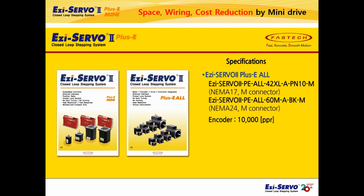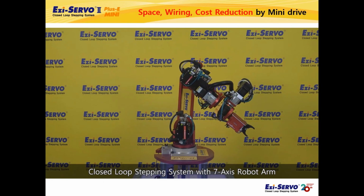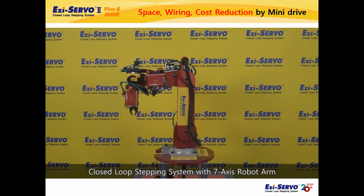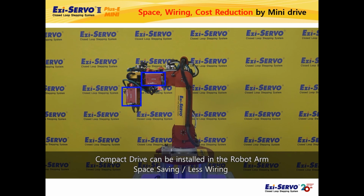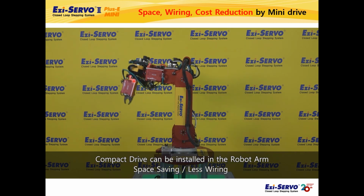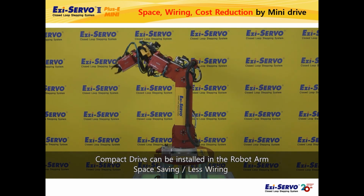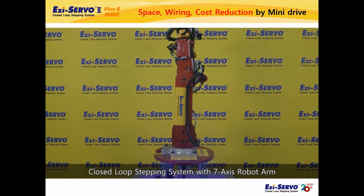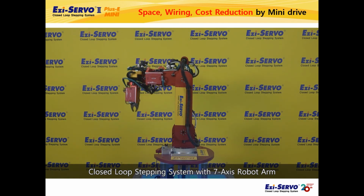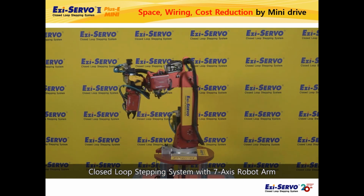The product names used in this demonstration are as follows. First, because the mini drive is small and lightweight, it can be installed directly on the robot body. Of the 7-axis, Ezi-SERVO 2 Plus-E Mini is applied to both the hollow and gripper axis. Therefore, the distance between the motor and the drive is very short, so it is possible to wire the motor cable and encoder cable very short.